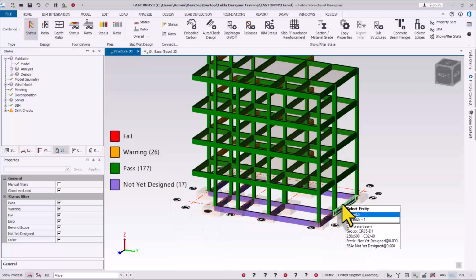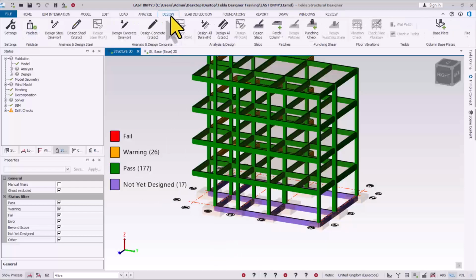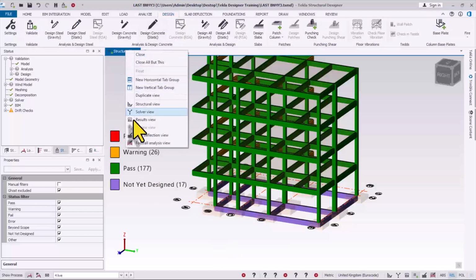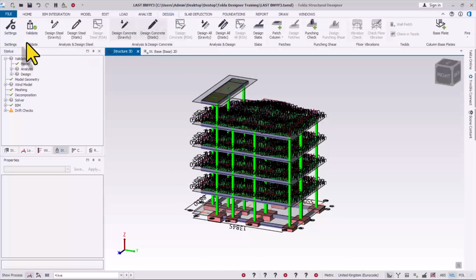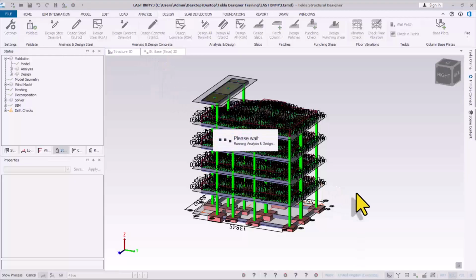So once you are okay with the foundation beam you've drawn, you just have to proceed, go to the design provisions, all right, navigate straight away to the structural view, and then under here you just use this option of design concrete statics. So just click in this provision. This will design the foundation beam successfully. It will first of all carry out the analysis before the design will take place. So we take our time to look at the design and see how to produce the detailed drawings.